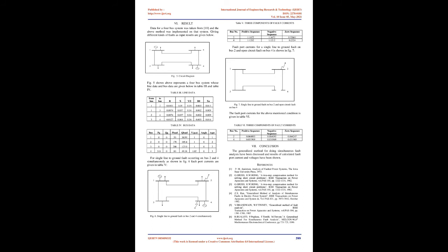Taking the case of a general short circuit fault at any point K on any line as shown in figure 2 and assuming the injected voltage. Flowchart 4 given below is an algorithm implementing the above given method. First and foremost, load flow is to be done to get the reference values to see the changes occurred after faults. Also, the open circuit voltage mentioned in equation 18 will be equal to the voltages obtained from the load flow. Hence, it is one of the major parts of the flowchart.